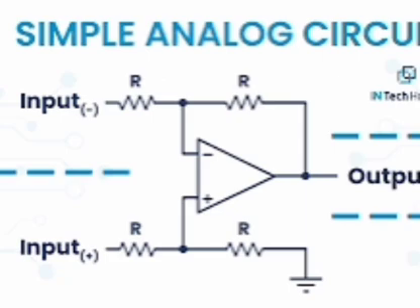So assuming beta to be large, S equals 1 plus beta by 1 plus beta into RE by RTH plus RG, meaning 1 plus beta is the numerator part, and the denominator part is 1 plus beta of RE by RTH plus RG, if 1 plus beta into RE is greater than RTH.